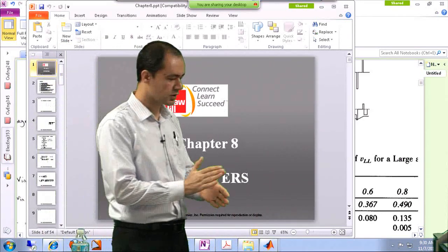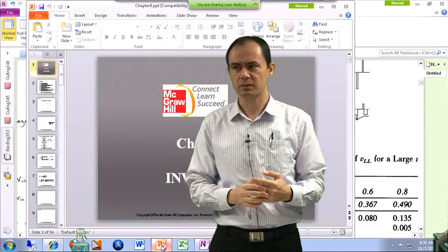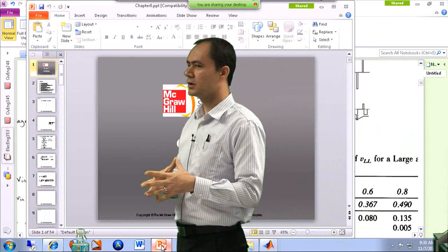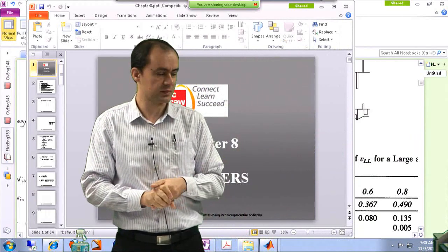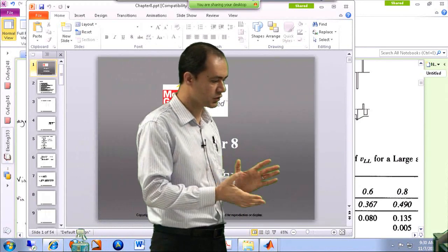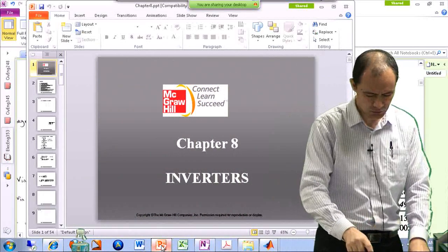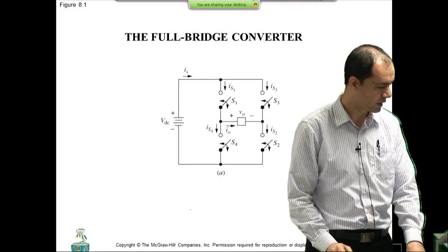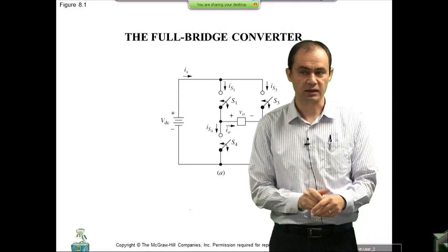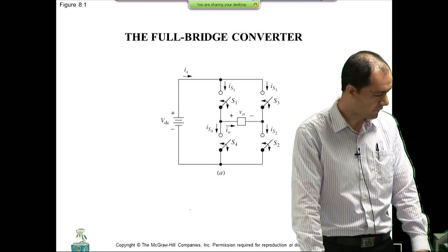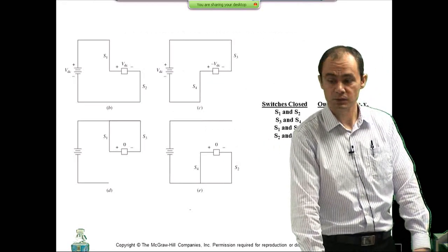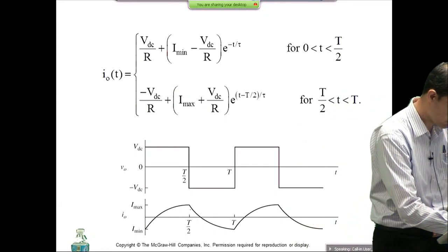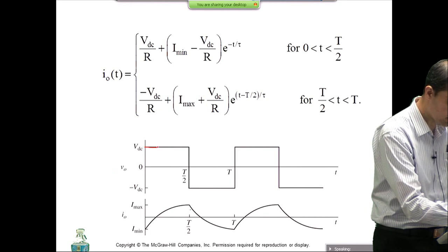Okay, so just a reminder, we are going to have our quiz number 6, I believe, on Tuesday, and the topics to be covered are anything that appears in this chapter 8 that we have covered in class, the inverter concept. What we did first was we looked at single-phase inverters, a topology like this. It's like an H-bridge kind of a thing. First switching scheme was a square-shaped switching scheme that gave us an output voltage which was a square shape, like this.